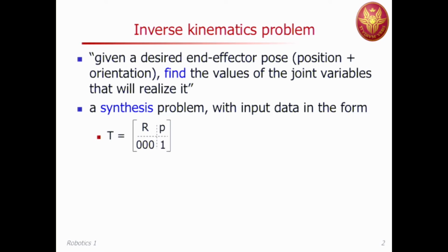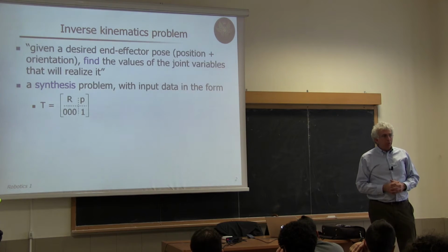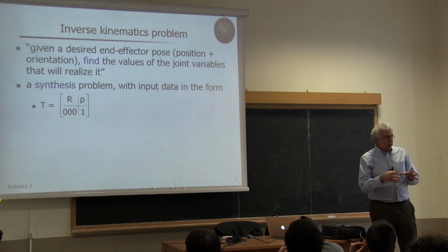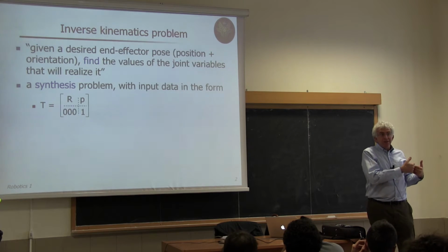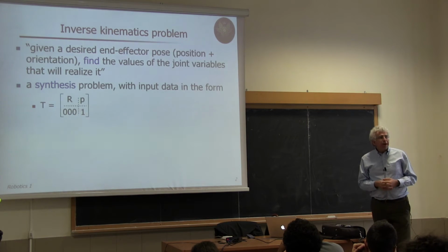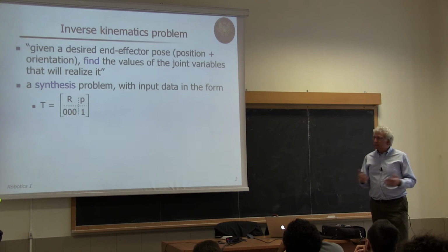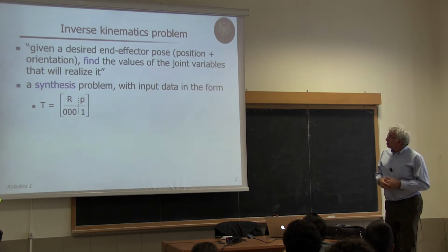While the direct kinematics is just analyzing and describing things correctly: setting the frames in an appropriate way, associating parameters to them, evaluating the Denavit-Hartenberg transformation matrices, doing the products, and that was it. Okay, so there are choices to make, but it's very systematic and there is no problem of finding a solution or not. While here we have to synthesize a solution, so to find a solution to the problem.